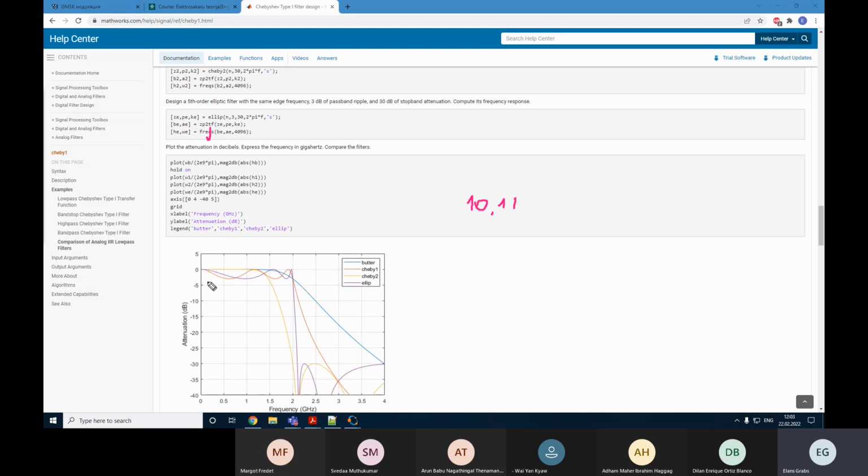And furthermore, exactly for Chebyshev filter, by the way, there is interesting property that it will accordingly specify how many times we will pass this middle line. So for example, here for the orange colored line, I can tell you that n is, let's count how much. Yes, so here we had 1 pass point, 2, 3, 4, and 5. So n is 5 in this particular case, yes. So this will determine how many ripples we have. So for 10, we will have 10 oscillations in these ripples. For 2, we'll have only 2 oscillations. But that's not really relevant right now.